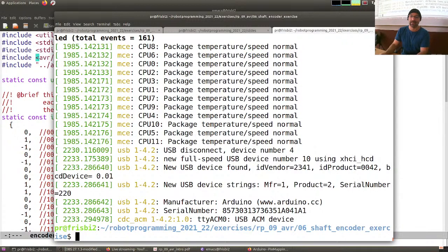So, if you do this, some of you might have had problems uploading the file on your device because maybe you have the Arduino mapped sometimes on ttyUSB0 or other things, especially if you buy clones or if you have multiple ones. Or if you do some mess with your serial line, then you don't know to which port it's going to map it. And so in this way you can find it out.